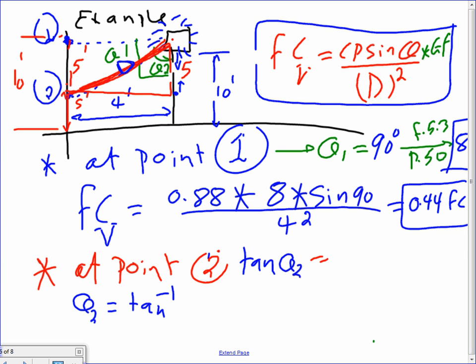On a test, you're going to grab this formula with you. If I ask you for a foot candle on the wall, plug it into this. If I ask you foot candle on the floor, you're going to use the floor formula. Make sense? Is that FC 1? This is FCV for vertical. The reason why I put the FCV here, guys, is because we're doing foot candle for vertical. The one that we were just doing before is the horizontal. Doing calculation of horizontal versus vertical.